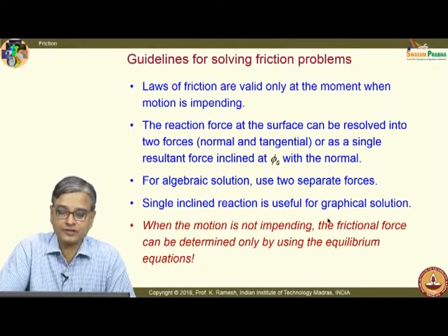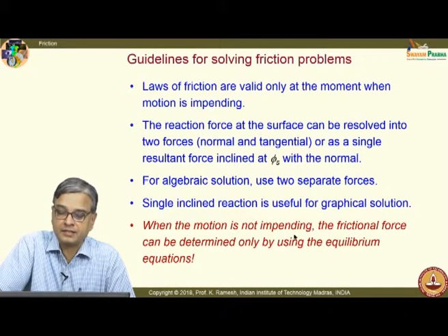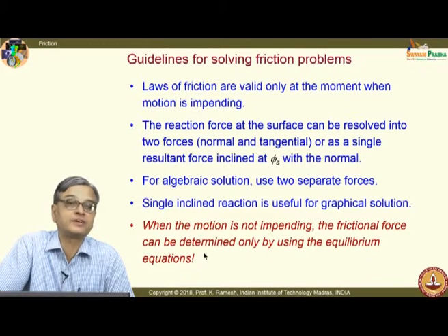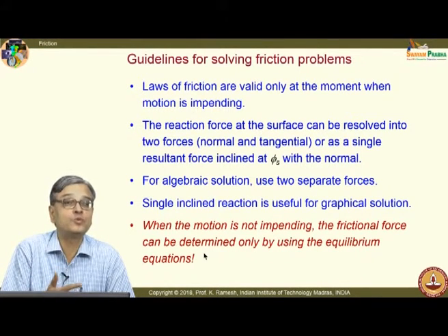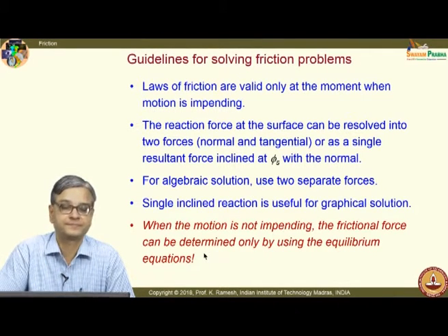If you use a graphical solution, a single inclined reaction is useful. And it is cautioned, when the motion is not impending, the frictional force can be determined only by using the equilibrium equations. You cannot replace it with mu times N unless the motion is impending.